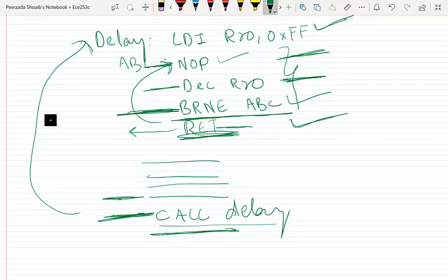That means these branch instructions, these calls, these jumps, these conditional branches, or even the return statement, take extra machine cycles to execute. Most of the other instructions only take one, and this is called branch penalty. The penalty is an extra instruction cycle to fetch the instruction from the target location instead of executing the instruction right below the branch.